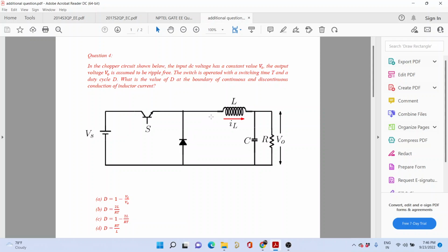However, it is a diode over here, so it would turn on, forward biased, and the current starts conducting in this loop. So the voltage across the inductor becomes minus V0, because this is plus, this minus, this diode gets shorted. So the minus terminal comes over here. So the voltage across the inductor becomes minus V0. Now you have been told that